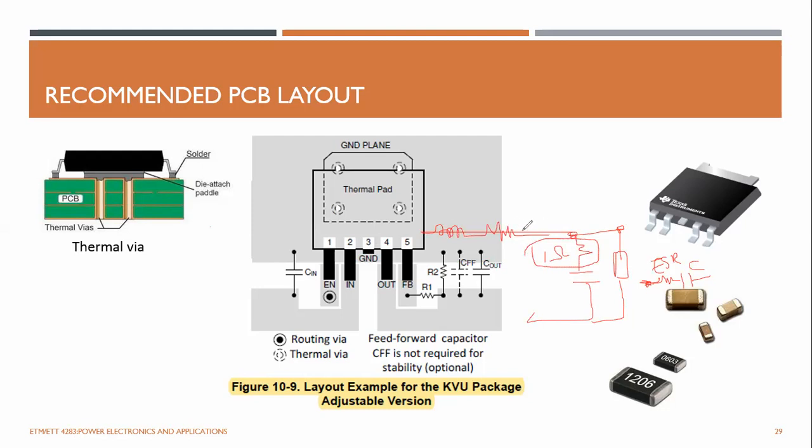But due to these longer wires or any other things, this will add more resistance. So now the equivalent ESR becomes 2 ohms. That might be out of the stable range specified by the manufacturer. So you will get some oscillations, right? And the inductance also affects. Therefore, always keep your input and output capacitors as close as possible to these pins in order to get the maximum performance,